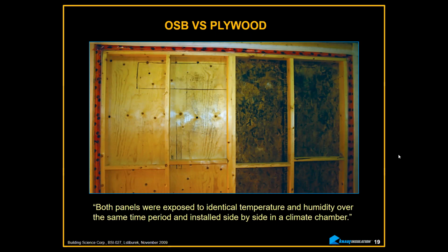And one of the things about head flashings on windows is I rarely see the ends of the flashing. Sometimes they're extended, sometimes they're cut right close. The two problems with flashing is a lot of them are tipped back towards the house. That's not a good idea. Instead of sloped away to the outside, and that the ends are not turned down.